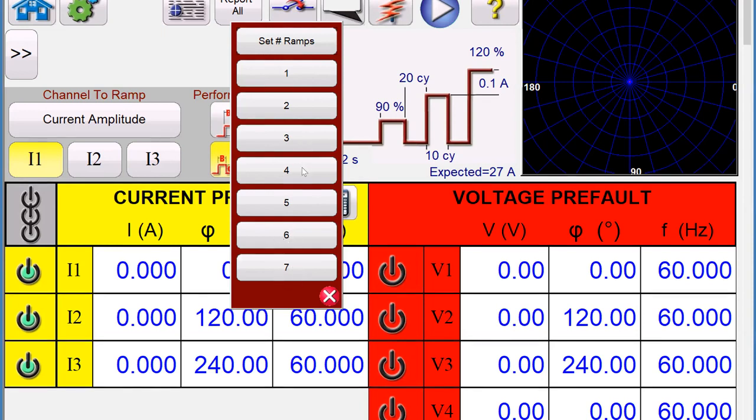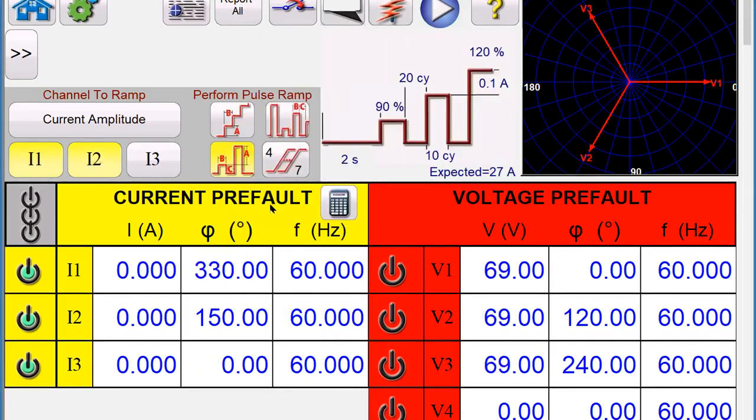Each one of these will be a little different. I will show you the A to B. We're actually showing 2 currents here, A to B, 180 degrees out, and we're also doing the same parameters, right? Because the 50 element is the same whether I do 3-phase, single phase, or phase to phase values. And then we need to know the expected value. This expected value is the setting that I pulled from the settings that you saw earlier.